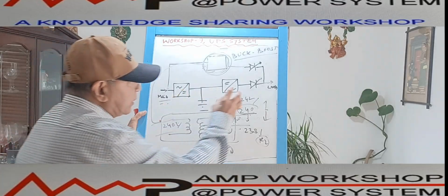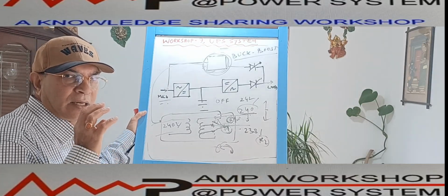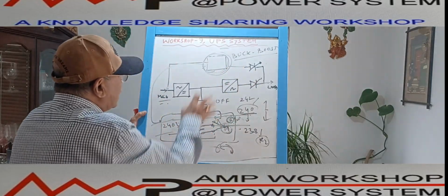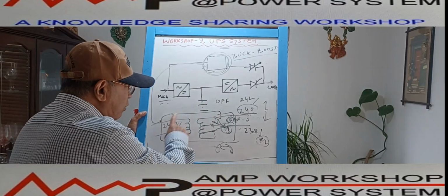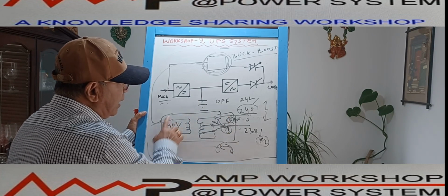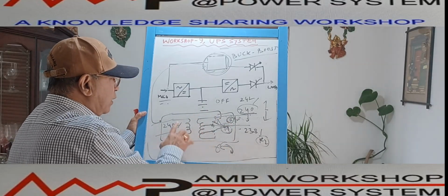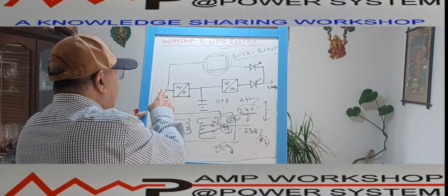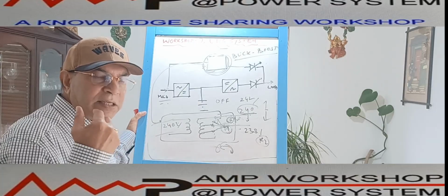So if the load is such that it can accept the harmonics but cannot accept the voltage variation, then we can use a buck boost transformer in this place. But what is the disadvantage of this? When you add an additional device, because 95% of the time this device will be live and activated, the transformer has additional loss. The loss will come into the picture, which will increase the power requirement, so automatically it will increase the bill.